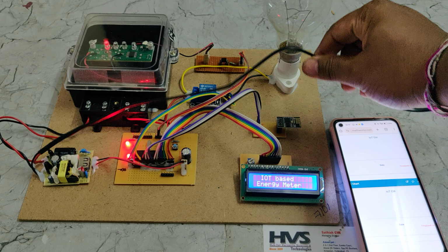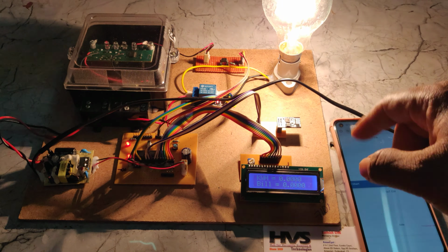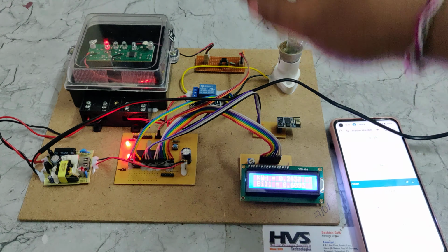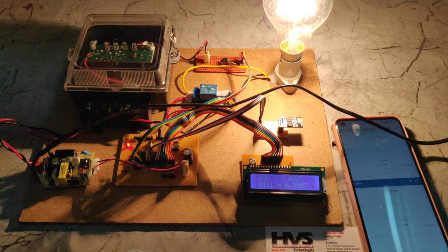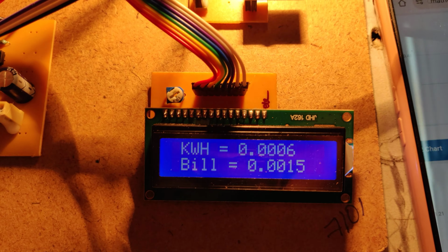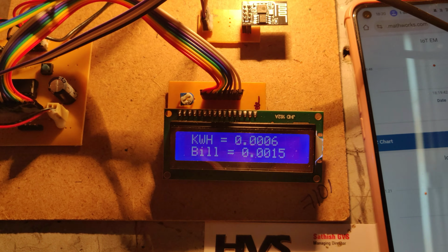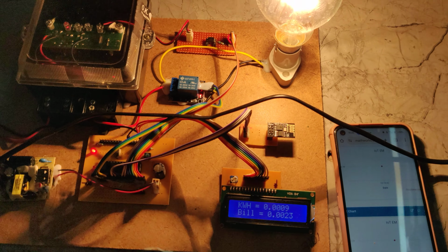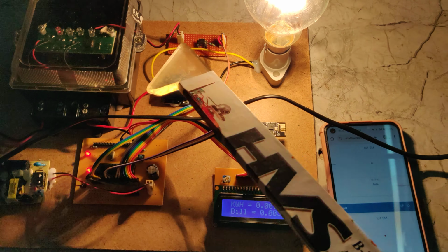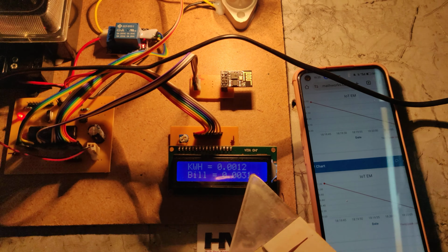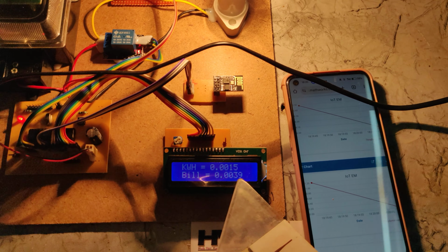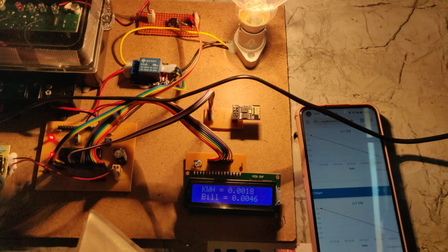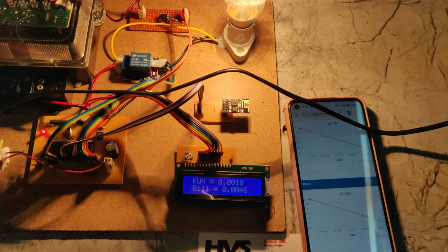Now once initialization is successfully done, the light will go on and off. Then the relay will get switched on. So on the LCD we can see that. As we discussed, one blink is equal to 1 by 3200 kWh. So it will keep being added whenever a blink comes from the energy meter through this optocoupler IC to the microcontroller. Whenever it crosses 0.04 kilowatt hour, then automatically the system will isolate the power supply to the load by controlling the relay.